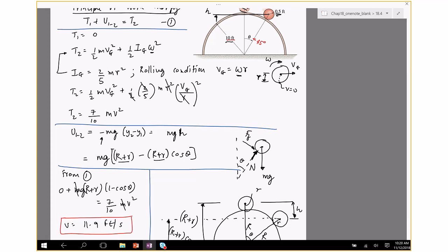Can you explain why friction does not work? Yeah. Because it's traveling a distance. Yes, but at that instant of time, the point of contact has zero speed. One way of thinking of that is F dot ds, but the other way is something called power, which is force times velocity. We did not teach that in the physics, and the integral of that is actually the work done. So since the velocity is 0, the work done is 0.